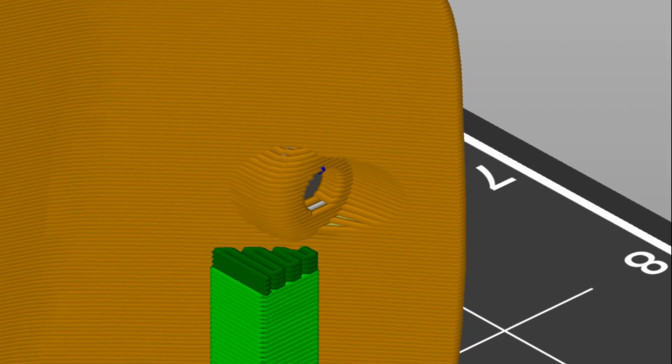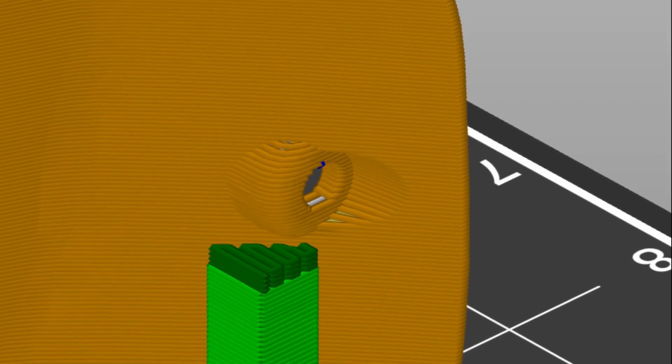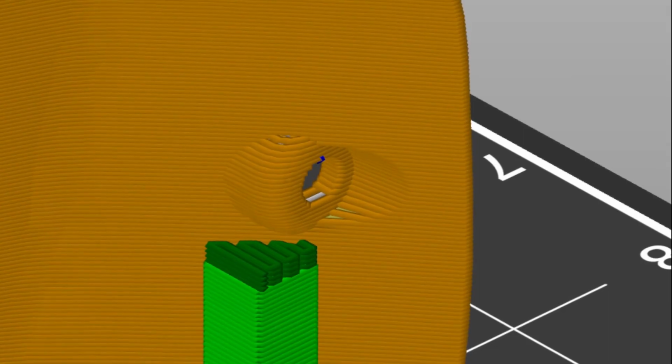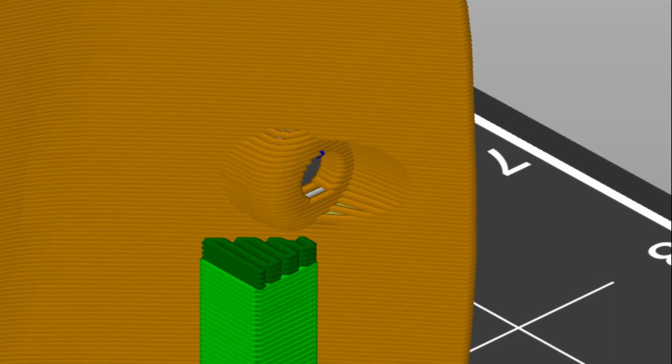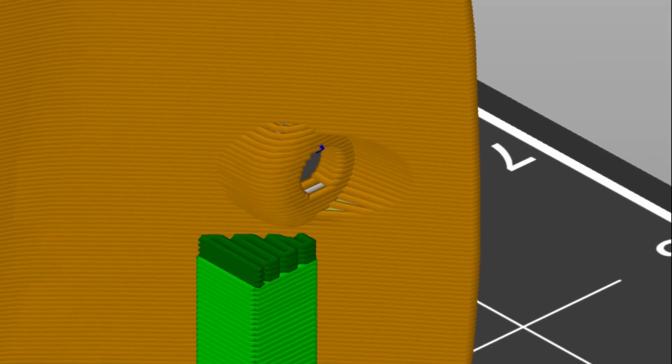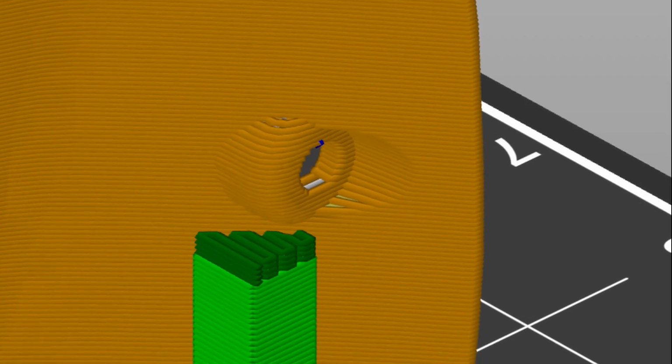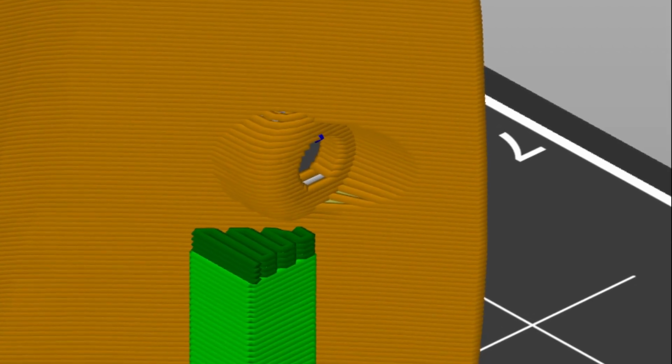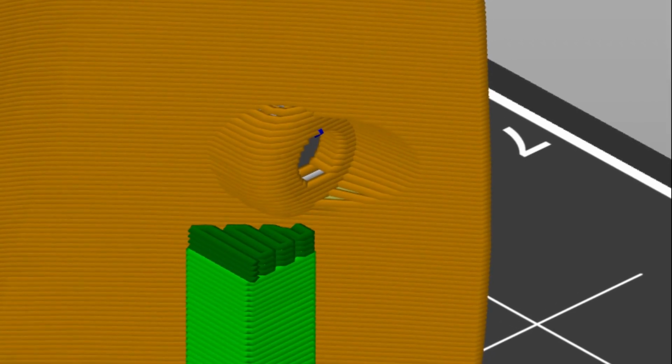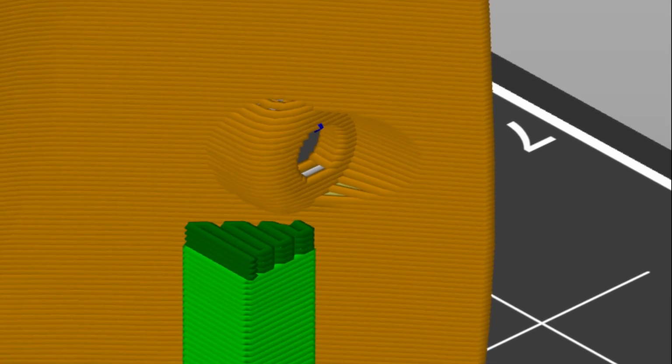This is why things like non-manifold edges, flipped normals, and holes in meshes cause problems. From the slicer's perspective, those errors make it ambiguous where material should exist. Before anything else happens, the slicer has to interpret that surface and decide what volume is printable.